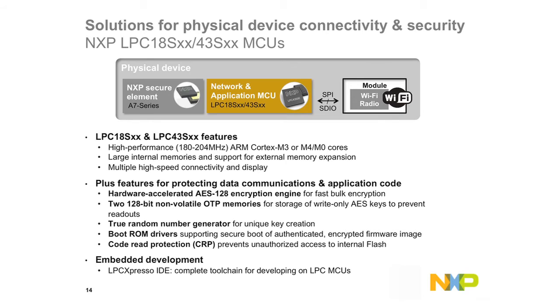So in terms of hardware, what's available, all of those security features can be done in software or hardware. There's a combination of things. Now, depending on who you talk to, they'll say, well, software isn't secure enough. There's never been 100% proven software. And there's a lot of clever things in terms of scrambling things in software to make it very difficult to find. I would say there are some benefits of having some hardware accelerated features in your microcontrollers or your external chips. One is it takes less code space because you no longer have to run the AES algorithm.